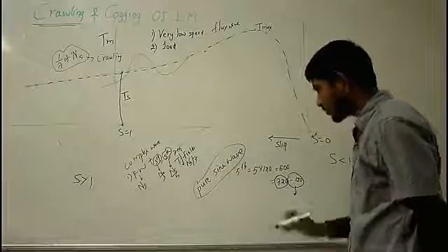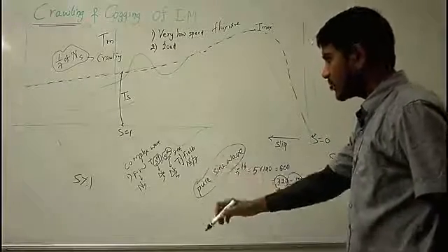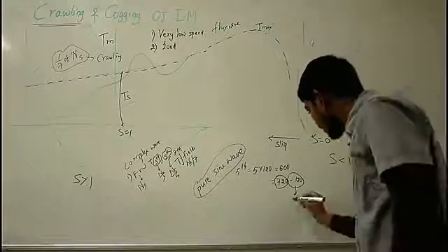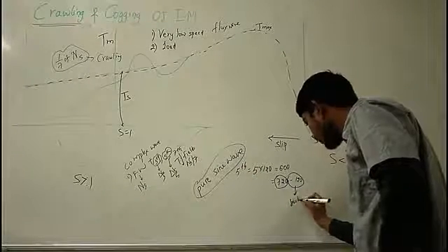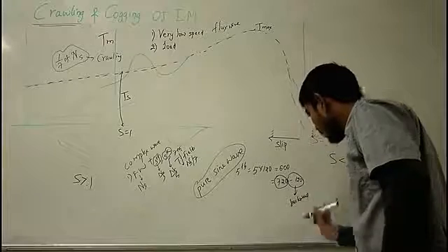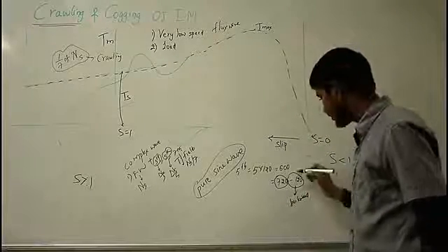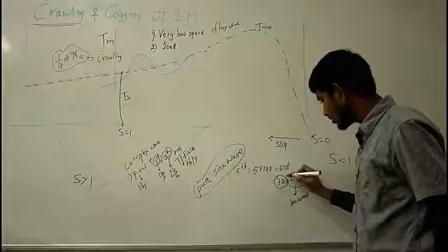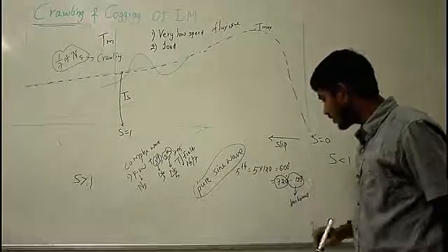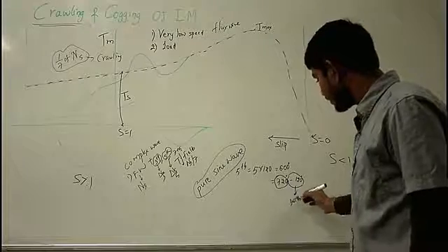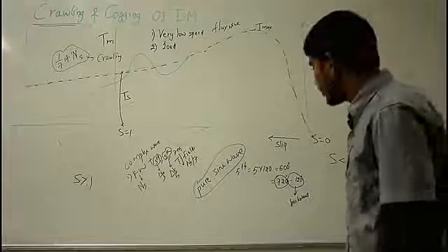That means the torque field produced by the fifth harmonic is a backward rotating field, due to the phase difference of minus 120 degrees. This is 720 degrees minus 120 degrees, which gives you minus 120 degrees, a backward rotating field.